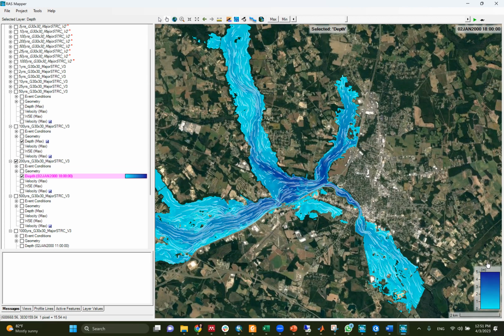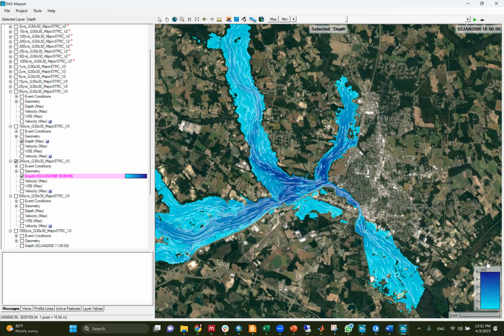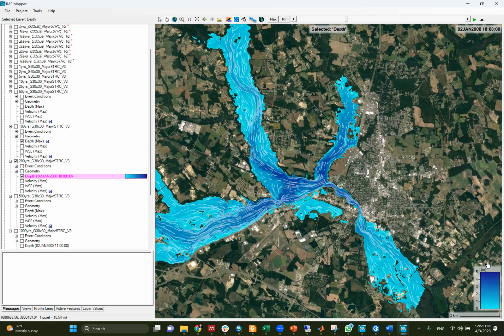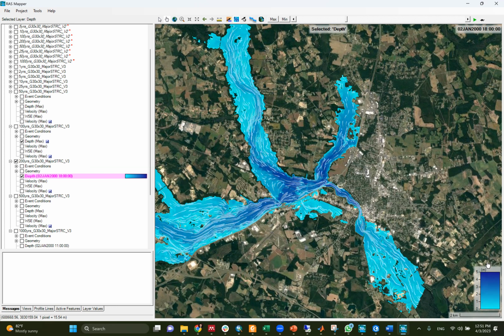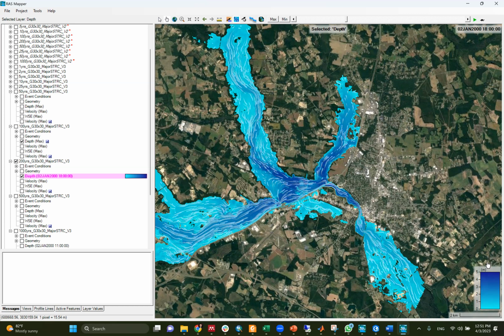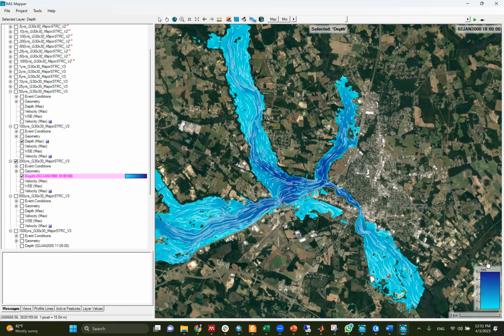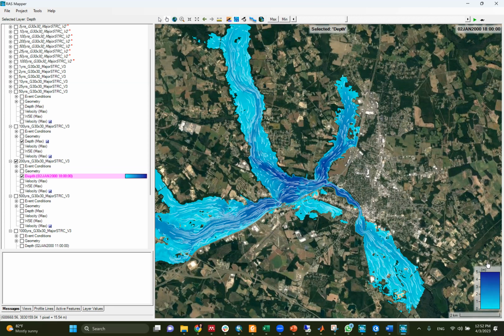So what if it's 0.8 meter, it will save me this amount of losses. So I will ask you to run a number of simulations for the flood barrier, like 20 centimeters, 40, 60, 80, and 1 meter. And you tell me how much loss reduction you will get from that. Also, you will be asked, for example, if not the entire 2,000 buildings do this, what if 20 and 50% of these buildings did it?